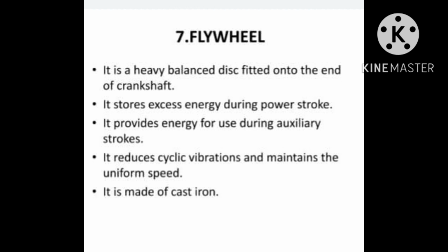Now this flywheel provides energy for auxiliary strokes when power is not generated or the engine is requiring power, then it provides the power. So it reduces the cyclic vibrations and maintains the uniform speed of the vehicle. Generally the flywheel is also made of cast iron.